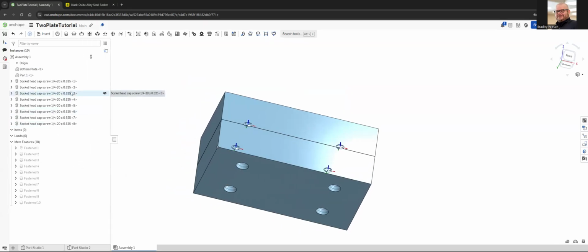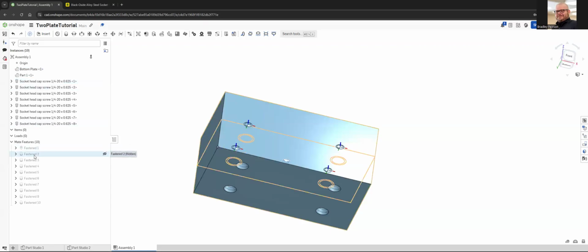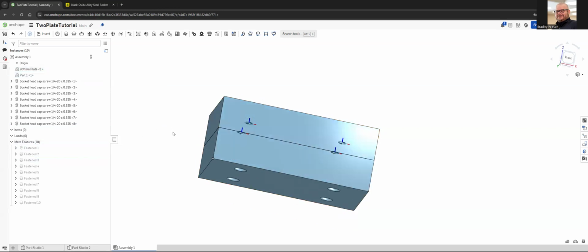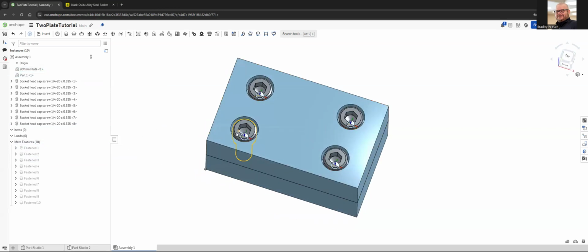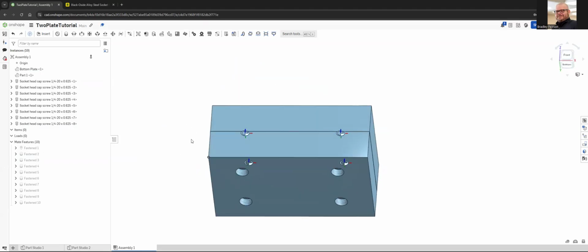And if I accept, let's see, can I make this wider so I can see? Yep. Now in Onshape, there's a little isometric axis symbol that indicates when things are floating, but it doesn't look like these are. It added a bunch of fastened mates, which I'm assuming means that we're totally locked down. Like, can I drag? I can't drag those screws. That is kind of cool.